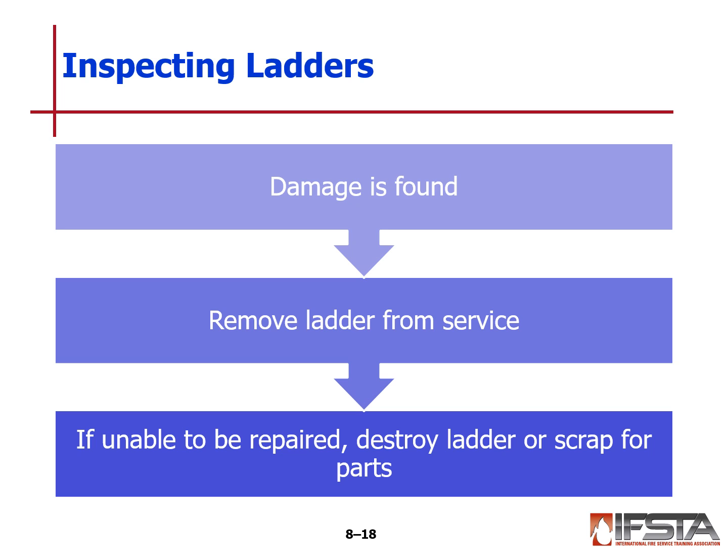I know a lot of times we back apparatus into something and bend that bottom rung, because your ladder sticks out from the back a little bit, and that bottom rung gets bent. At that point it's out of service until it is repaired. You can replace rungs if it doesn't damage the beams to the point where a rung can no longer be attached. So that's one example.